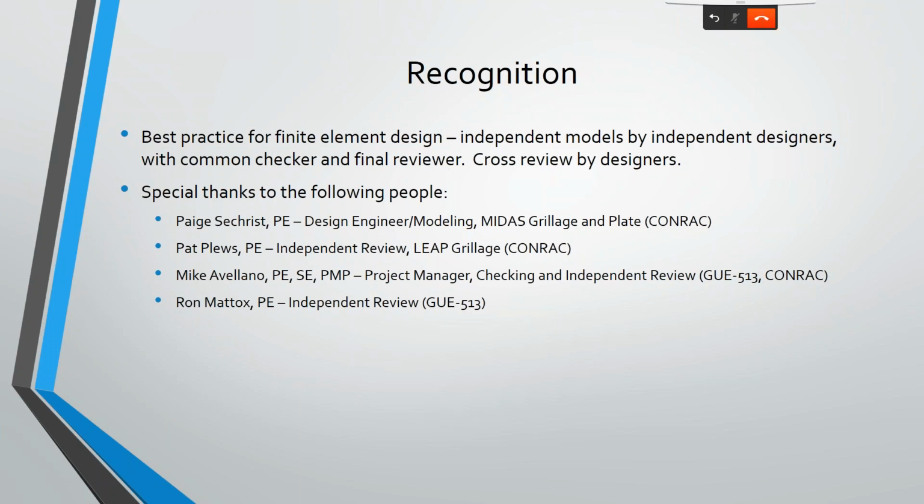And that's partly where some of those differences come from as well, because when you have a different designer doing it, they may set up the loads a little differently, that kind of thing. Some of the properties, like using an n of 7, 7.5, or 8, that kind of thing can change your composite stiffness slightly, which changes your distribution. So there's a little bit of that just to be expected.